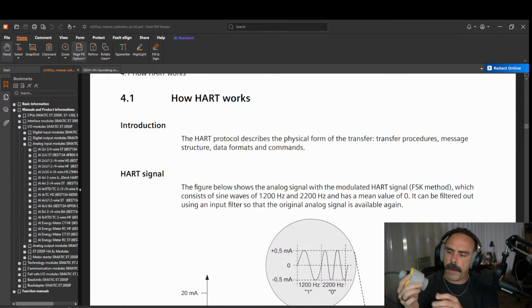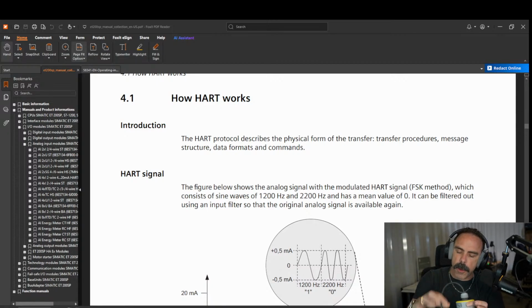This is really good for dry, dusty environments like that. But it only has 2 wires that actually come out. I guess technically there's a shielding ground on it, but you have 2 wires that come out, and it's a 4 to 20 milliamp transducer.